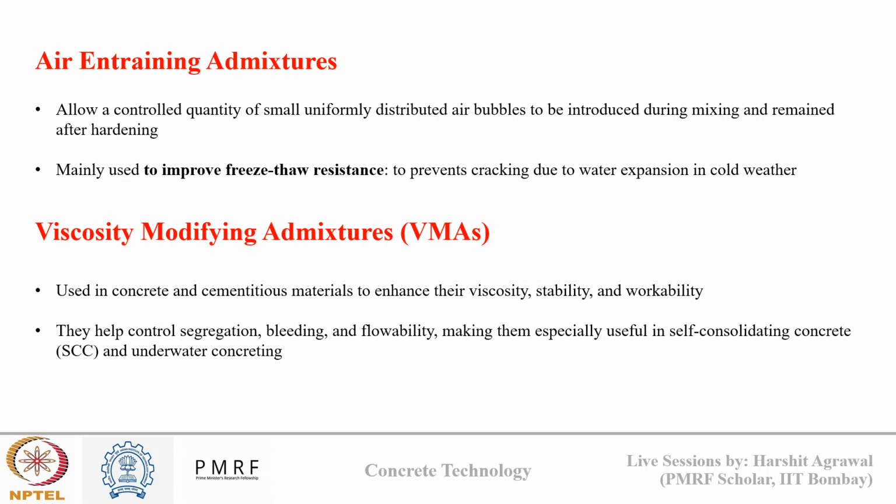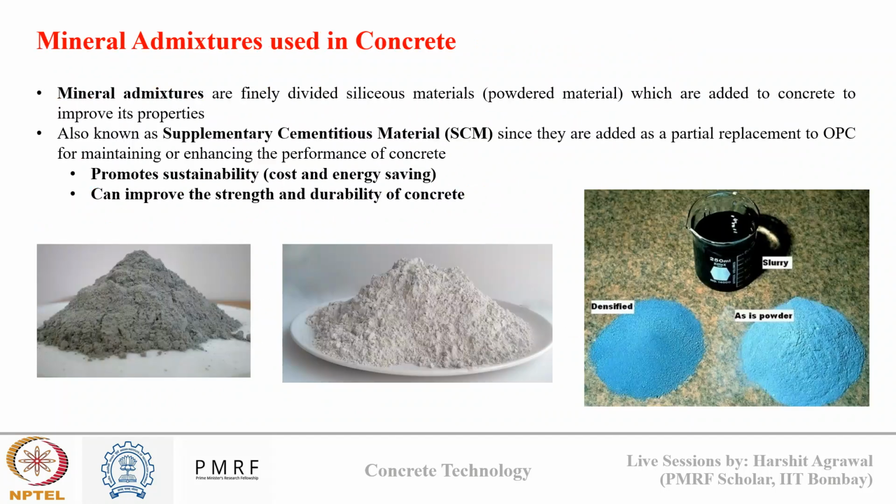Then we discussed air entraining admixtures and viscosity modifying admixtures, and particularly paid attention to where they are used. Air entraining admixtures are important in cold weather concreting where freeze and thaw action is a major durability issue, while viscosity modifying admixtures are used in self-compacting concrete to control segregation and bleeding issues.